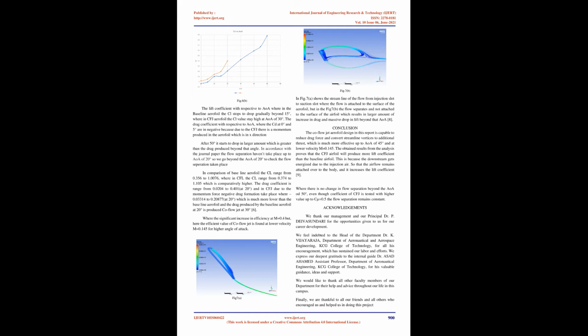In Fig.7, A, shows the streamline of the flow from the injection slot to the suction slot, where the flow is attached to the surface of the aerofoil. But in Fig.7, B, the flow separates and is not attached to the surface of the airfoil, which results in a larger increase in drag and a massive drop in lift beyond that AOA.